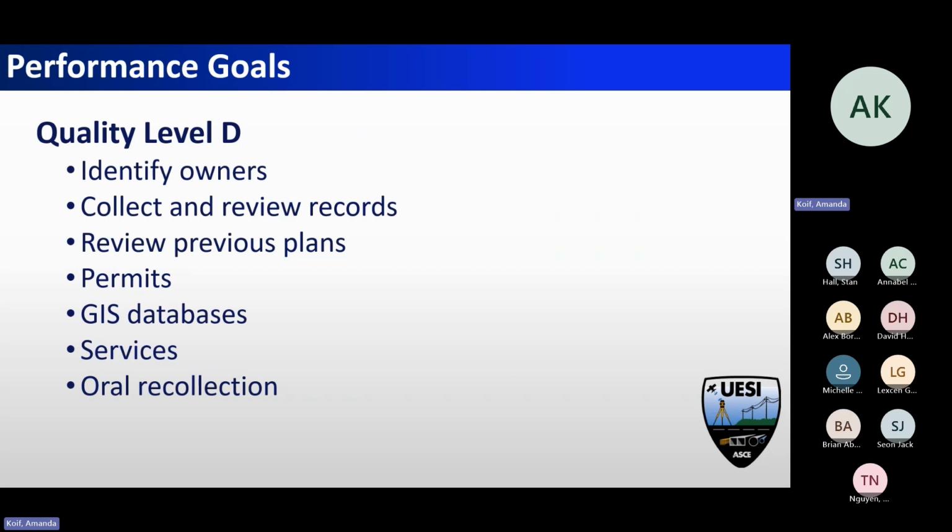So you can just obviously pull that information in and use that for level D services. If I see a water meter, but I see a fire hydrant, anything like that, but I don't have any plans for a water, I still could probably assume that there's going to be a water line there somewhere. And if you have enough hours or maybe some other information, you might be able to just make an engineer's guess and then put a note on there that says, based on engineering judgment, I'm adding this water line, just so you know that it's there and we probably need to account for it or maybe do some additional investigation.